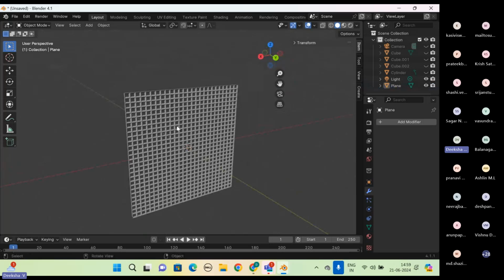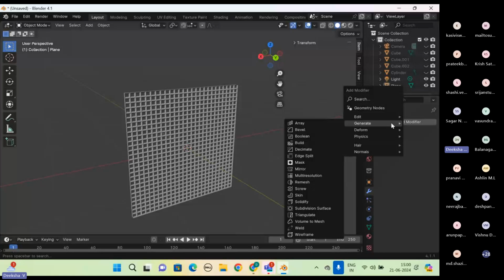This modifier will now have no more role in your body. So that is an important tool you have to remember. Especially while mirroring, if you're done with the symmetrical part and you don't want anything else to copy, then just apply your modifier and continue with the work. So that is another option.